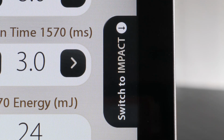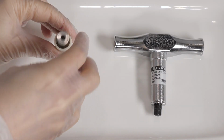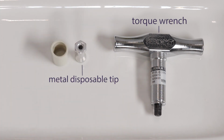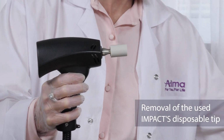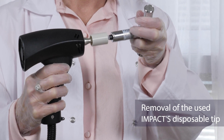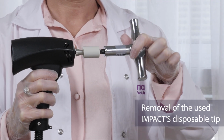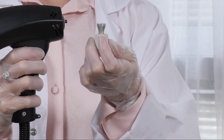Press Switch to Impact. To attach or detach the Impact's disposable tip, there are three parts: the torque wrench, disposable tip, and the plastic socket. Connect the plastic socket to the used disposable tip. Connect the torque wrench to the plastic socket. Turn the torque wrench anti-clockwise. Remove the used disposable tip.